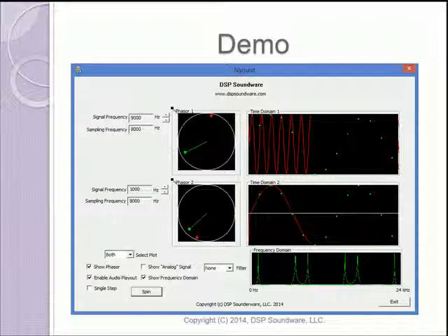Rather than state that you must sample at greater than twice the bandwidth of a signal, we've shown what happens if you don't do that, and clearly you lose information and you introduce ambiguity into what you've sampled. You don't really know what you have. A 1 kilohertz signal in appearance could look like 7 or 9, etc.